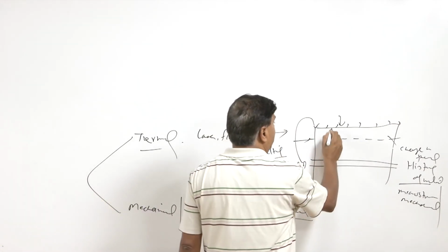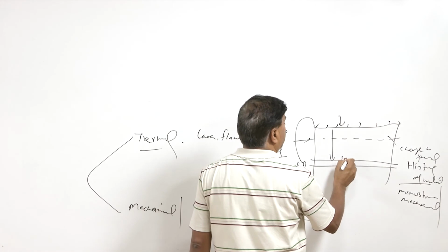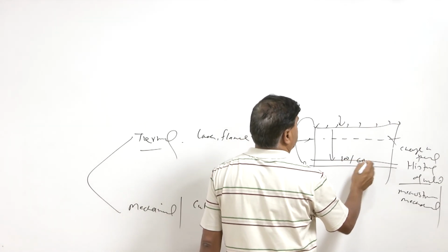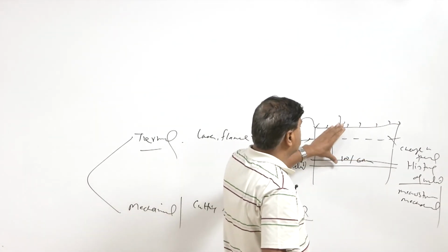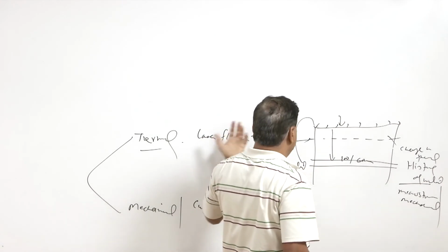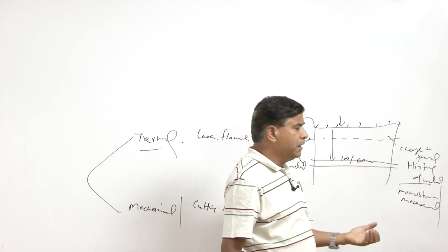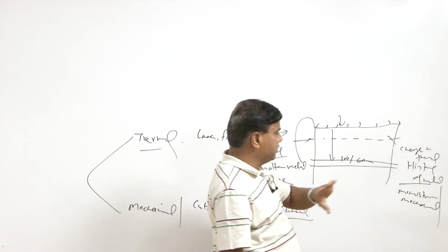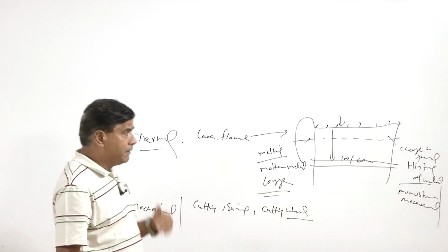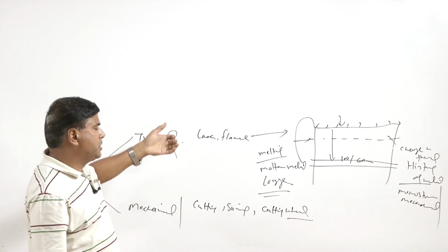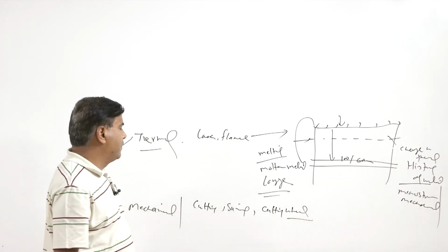It may be, say, 100 mm or 60 mm, so that the extent of damage to the component is less. Depending upon the heat source this distance can vary, and it must be sufficient to avoid any kind of thermal damage to the region which is to be investigated for the failure analysis purpose.